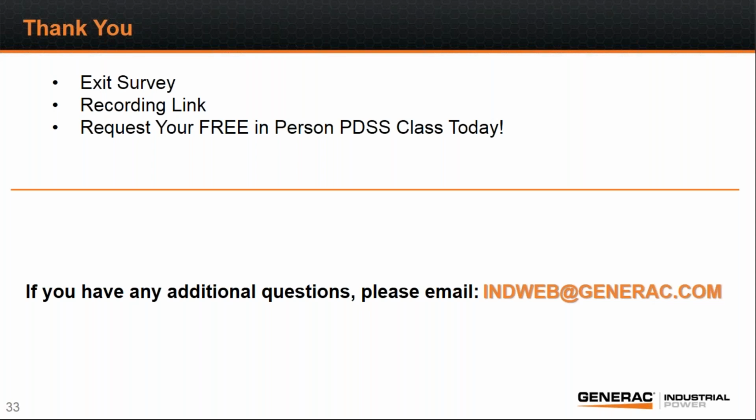Don't use leading power factor loads, which would be power factor correction caps, for instance, within your power system. Or it could be a lot of VFDs with harmonic filters that are running very lightly loaded. That could be another situation where you run into a leading power factor condition. Generally, we don't run into problems with low power factor, other than the motor starting discussion we're just having. That becomes part of the generator sizing. During that starting phase, we get a lot of LRA, a lot of hit on the alternator, and we need to plan for that voltage dip.